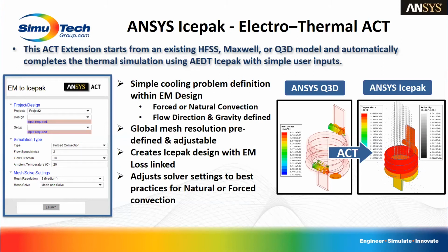But what happens is the Icepack design is created behind the scenes, so you never really have to open up the Icepack version in Electronics Desktop. The link is done automatically. The entire generation of the Icepack model is done automatically using the existing model in the EM product. And it will adjust all the solver settings to the best practices depending upon how these options are set in your ACT window.